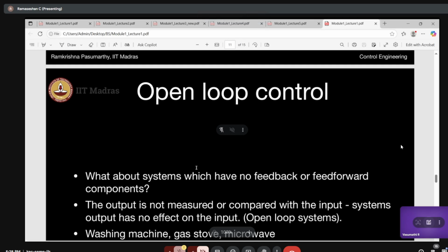But when it comes down quickly and the system has come to 25, you cannot stop it, right? Even if you stop it instantly, it will go on cooling further. The system will take some time to respond. Yes, sir. Correct. And then you will decrease the compressor suddenly, at a very high gain, and it becomes uncontrollable after that. Oscillations will happen. And if you are very greedy, the oscillations will grow instead of decaying.